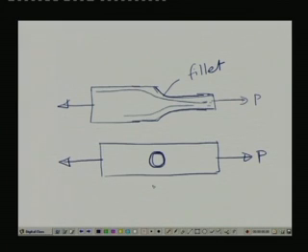Now, a clever design could be like this: you put two small holes, one before the large hole, another after the large hole. I need not explain; you understand that there will be no sharp change in the stress lines, but a gradual change in the stress lines compared to what we had if there had been only a big hole.